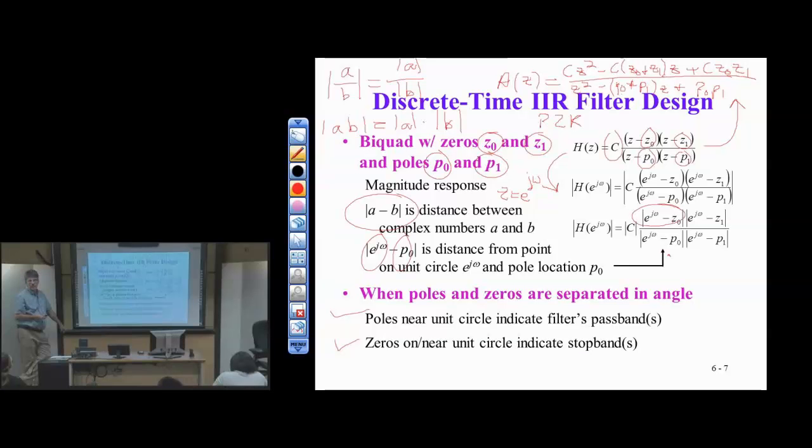Now, is that a problem for zeros if they move around? Probably not. A little change in the magnitude response, maybe. Doesn't affect BIBO stability. But if the pole locations decide to move around, why is that bad? It can change the BIBO stability, and this is exactly what happens in practice. So what we like to do is limit the amount of expansion from the factored form to the unfactored form, and we control that in the biquad. Here we just have one expansion.